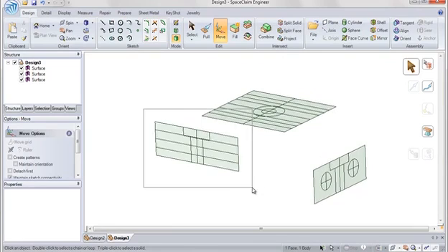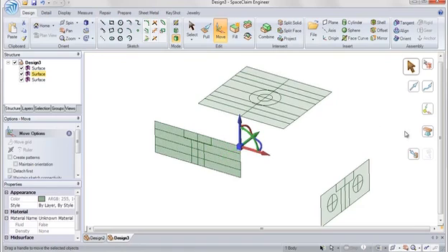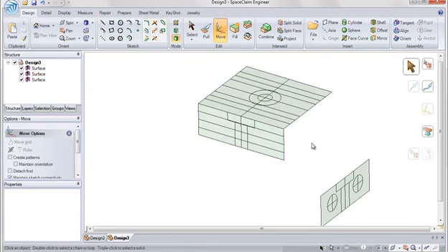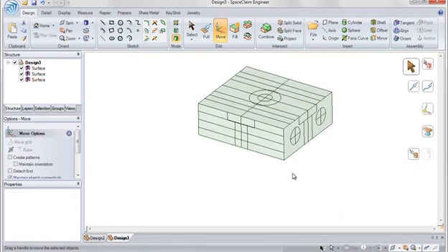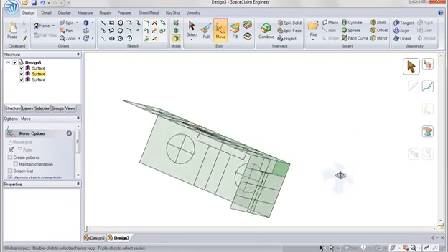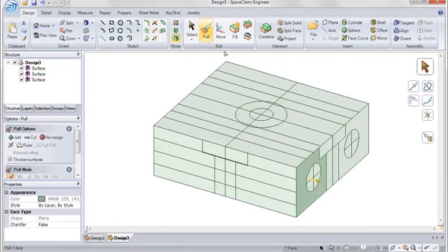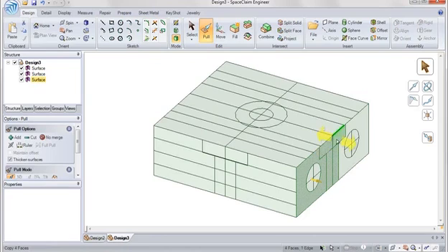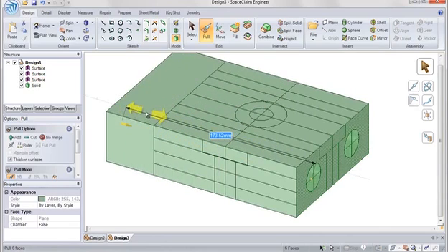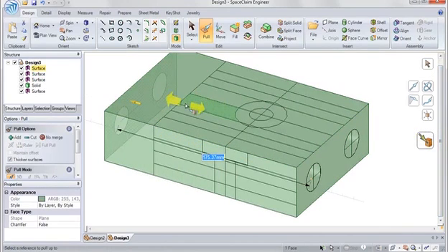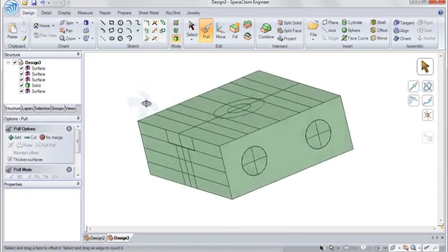And now I'm just going to position them correctly. So I'll go ahead and grab one of those views, re-anchoring my move handle, and using the move up to command to move them directly into place. Getting all three views in a 3D layout. Now I can easily go in and pull on any of these surfaces to create solids. So I'm just going to go ahead and pull my selected surfaces, creating a 3D block and using the pull up to command to reference the other ends of these faces to get the exact geometry I want.